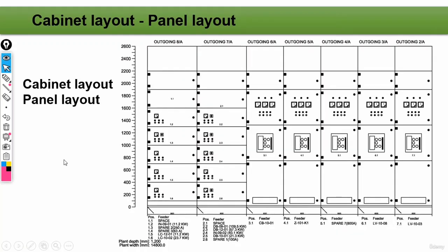Guys, alongside components arrangements, we also have cabinet layouts. Through this, we can basically get, you can say, a general view, a general layout of the entire electrical panel. For example, this current one includes 7 cells, with each cell containing a feeder. More precisely, each one of these equipments is actually a feeder. And they would basically be used for controlling a single-phased or 3-phased motor or direct current motor. In other words, a DC motor. And then in this cabinet layout, we can see emplacement areas or locations for other equipment such as push buttons or signal lamps or even circuit breakers, aka power switches. And yeah, basically these would be the information that we can get out of these diagrams.